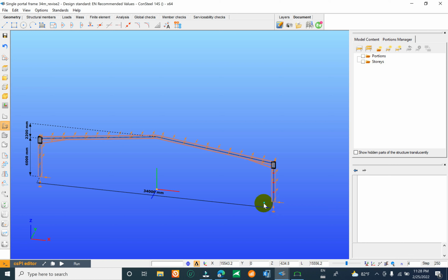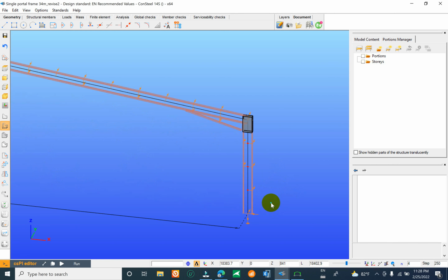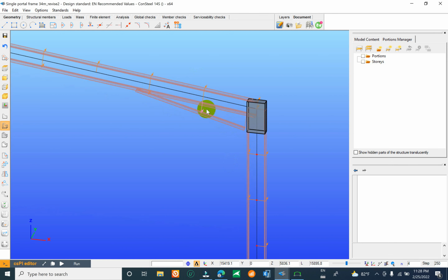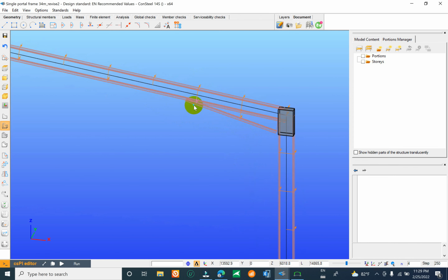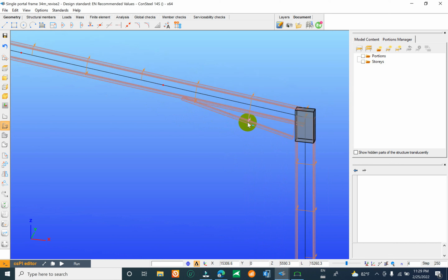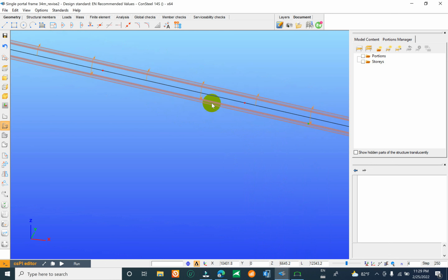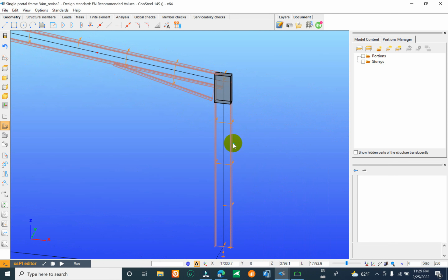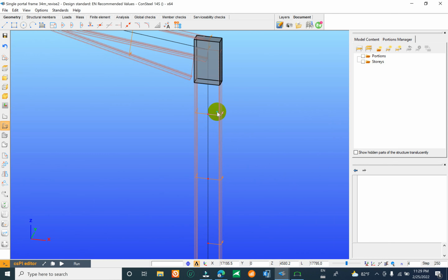the support. The very important locations are location 1, 2 and this location 1, 2, 3. These three locations are very important to keep our structure stable and out of plane. Here we just like to model the purlin, the upper purlin, and add the lower restraint against torsional lateral buckling. So we have to add at the bottom, and we skip one and add to the bottom again, and add to the bottom again, and for the column we apply the same concept.